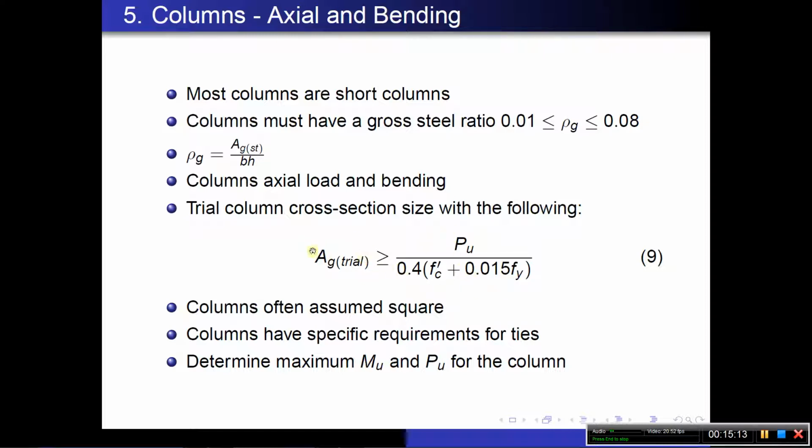Now this is just going to give you an estimate. It's not going to be perfect. You might have to make some adjustments in the course of doing your design. You may find that it's either too small or too big, but it will at least get you started. We oftentimes will assume that our columns are square, but it is true, sometimes they are rectangular. But for your purposes at this point, assuming a square column is probably a decent idea.